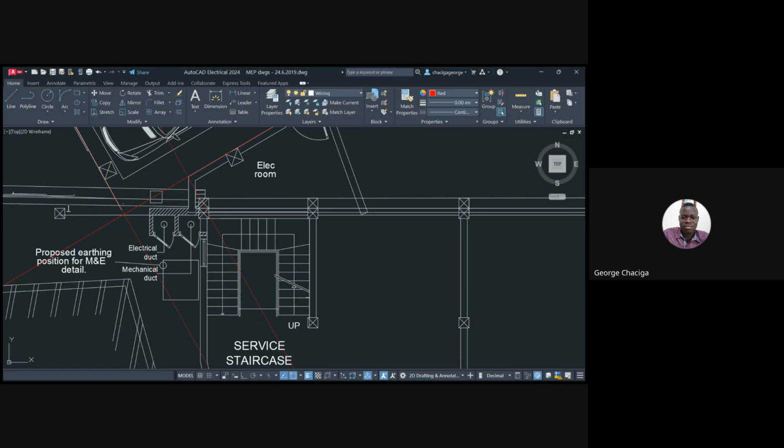Since we've selected our 3 fixtures, what would be our spacing? Our spacing would be about 4.3, which is fine. Are we together? Then to know the offset from the walls, you multiply this by 2. The 3 that you've got, multiply it by 2, which gives us a 6. As we did for the other, we had 4, we multiplied by 2. That's why we divided there by 8. So here we are dividing by 6. We get our offset from the walls, which is 2.19 meters.